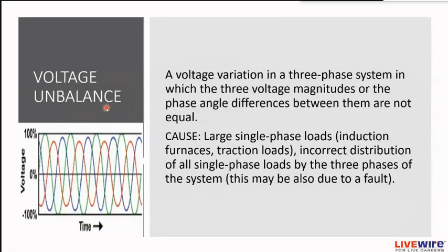The causes of this voltage unbalance are large single-phase loads. If we connect any large single-phase load on one particular phase, there will be some voltage unbalance. This causes negative sequence current to flow in the three-phase loads, and this is harmful to our loads. This basically occurs when induction loads are connected. It causes overheating and noisy operation of the loads due to this voltage unbalance.